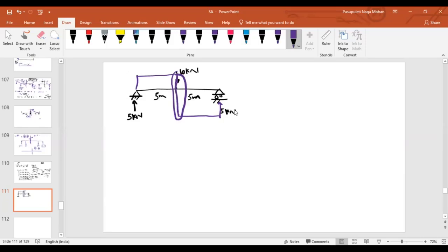As you can see, whenever there is a concentrated load acting at a joint or not at a joint, or if there is a concentrated force or reaction acting at the point where we are finding the shear force, we cannot define it exactly at that point mathematically, because the left side limit and right side limit will be different.